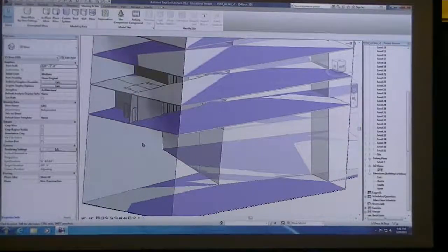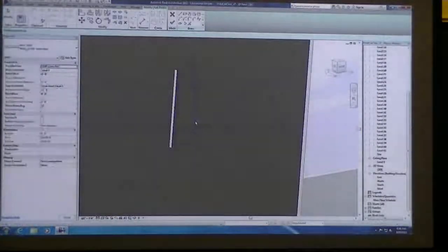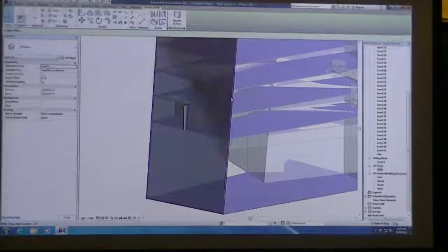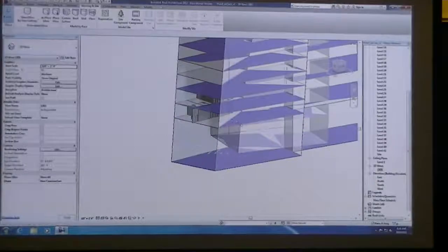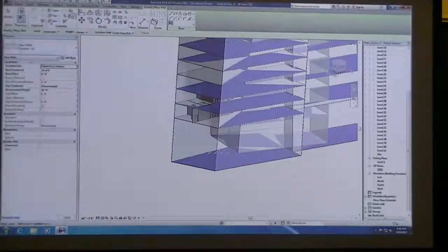Can you go real quick again how you had that wall on the side of that curve, the wall you created? The one that's actually following the mask? Yeah. So just like in the floor assemblies, when we created our mask floors and then applied a floor to that, we can also go to wall, click on wall by face, and choose a particular wall in your drop down menu, and then you're picking a face, and I tabbed over till I found the particular face I wanted to select.